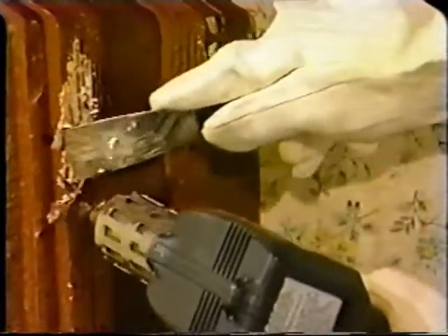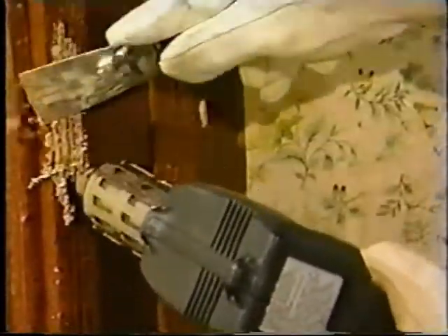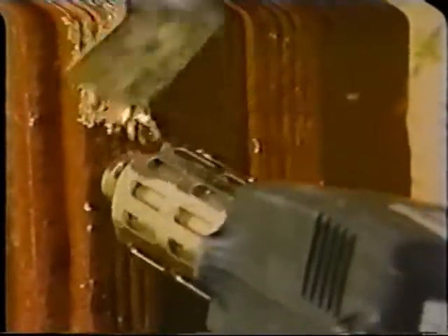Lead-based paint may also be removed on-site using a heat gun. This process consists of applying heated air to the painted surfaces with a portable hairdryer-like instrument. The heat softens the paint so it can be removed by scraping. Since the paint is soft and no longer brittle, scraping does not tend to create additional dust.